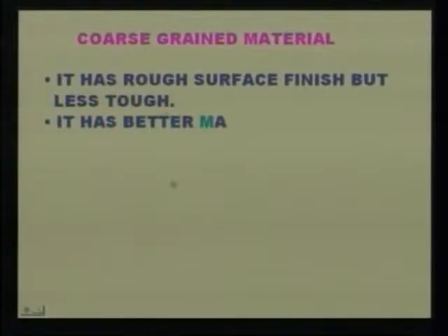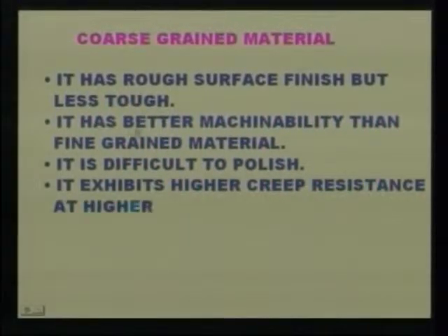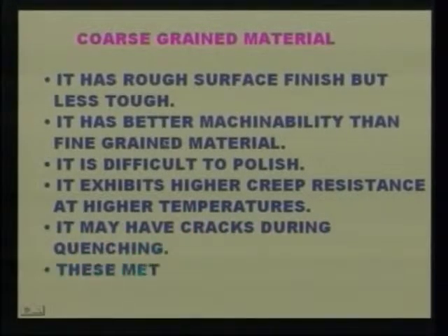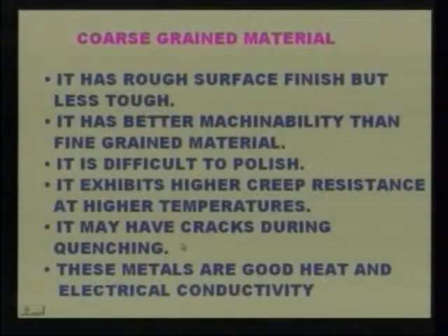Now you can see coarse grained material. It has a rough surface finish but is less tough. It has better machinability than fine grained material. It is difficult to polish. It exhibits higher creep resistance at higher temperatures. It may have cracks during quenching. These metals have good heat and electrical conductivity.